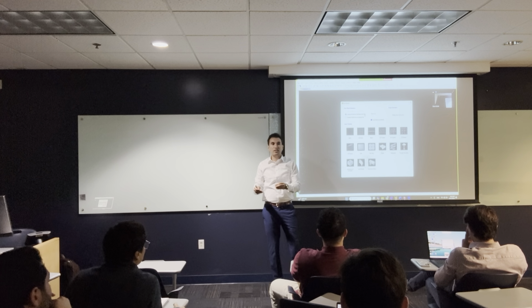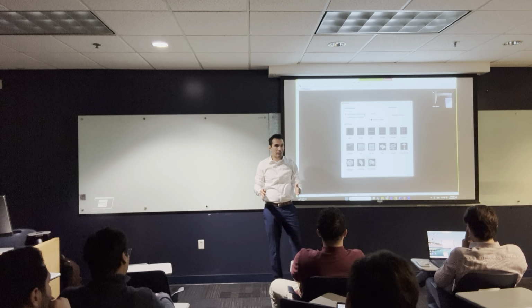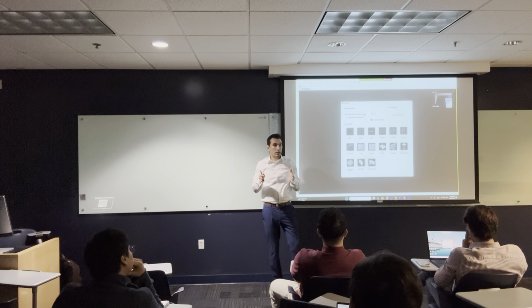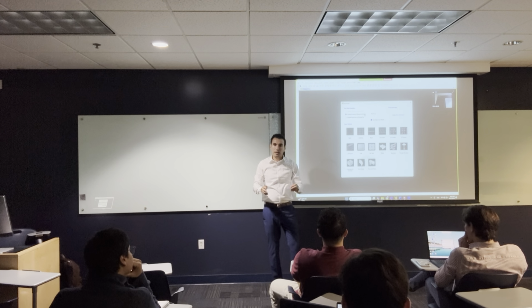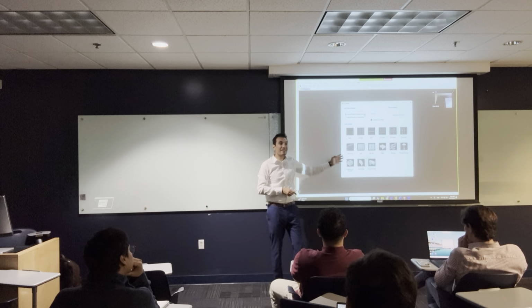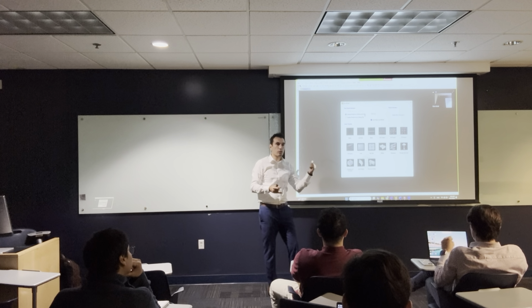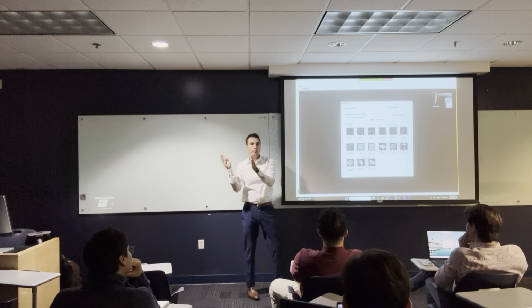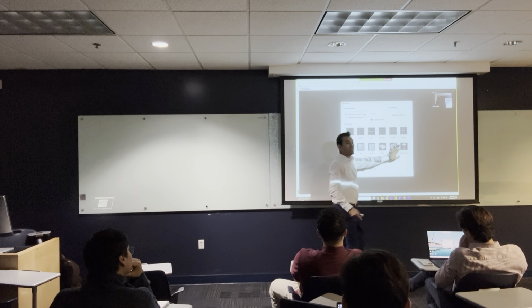As I said last time, ETABS is the best to use for what? Do you guys remember? ETABS is good to do structure analysis for tall buildings, multi-story buildings. SAFE is only for slabs, but SAP 2000 can do, for example, a swimming pool. I would do it with SAP 2000. If I have a retaining wall that holds soil behind it, I do SAP 2000. If you have a tank, I do it with SAP 2000.